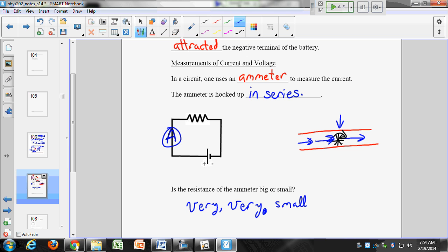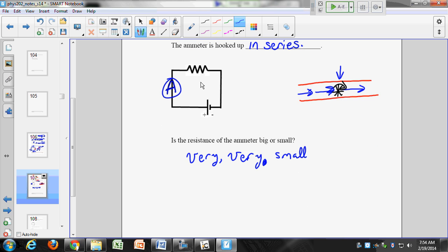Anyway, so the ammeter has a resistor inside of it, and you can see that resistor right here. It's just this little coil of wire, all right? And so you'll talk about that resistor next week. I think this is called the shunt resistor. Maybe it's called the multiplier. Shunt is your resistance. So you see a little coil of wire up there, on the top of that plastic case. That's your resistor inside the ammeter. It's a very, very small resistance, basically just the same as a piece of wire.